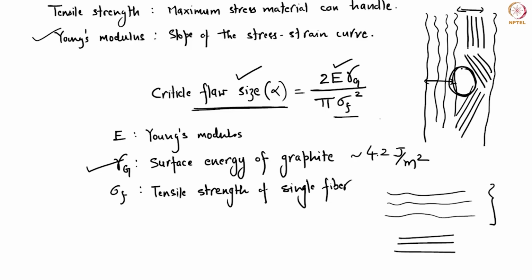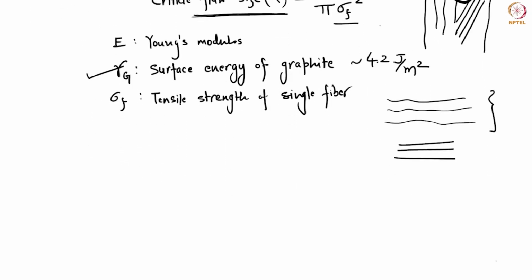Again, if the fiber is very thin, there is a high probability that some of these flaws will anneal out. Also, in the case of thicker fibers, some of them will anneal out, but not all of them. Some may remain trapped, and these are then the weak points in your fiber. That's where your fiber will break. So this is just to tell you that just increasing the carbonization temperature is not enough.